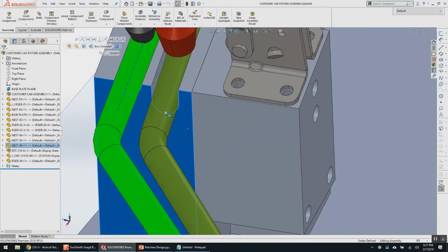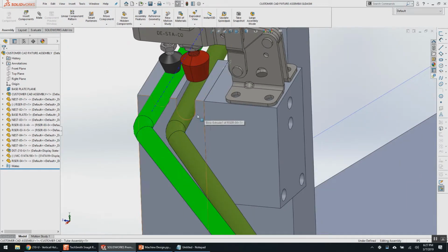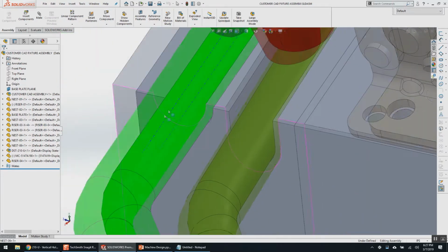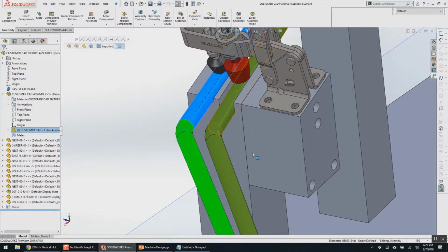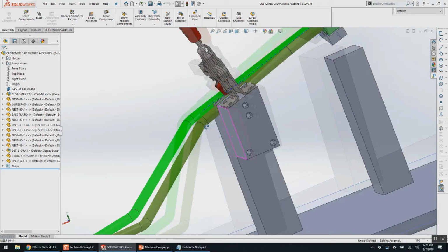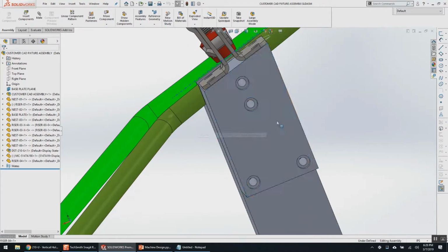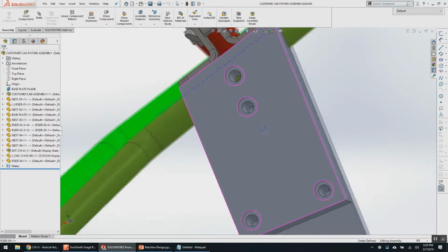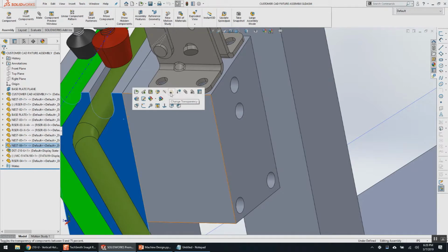I don't know what material this is. I would assume this is making part contact. It would have to be steel. Jerry's not here. I'm not sure. A2? I don't know. Jerry would have answered me that if he was here. I'm guessing because these are just light aluminum tubes, I assume. It might just be like an aluminum with a hard coat. You could do like type 3 hard coat. I don't know. But the point is SolidWorks defaults at double the diameter, which is like a 99% always case. If you're going to rip out 4 quarter 20 threads on a Destaco clamp, it's probably a problem.